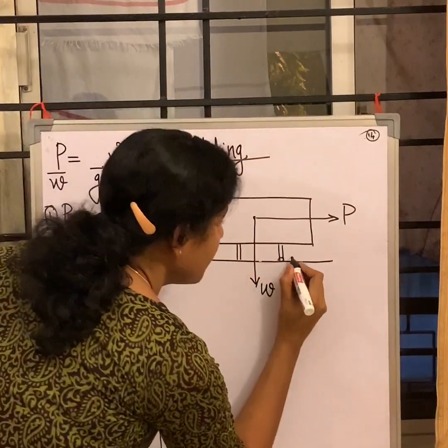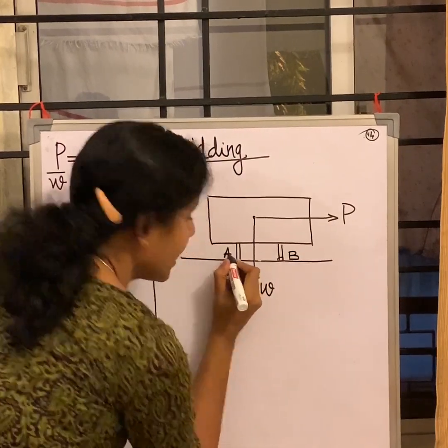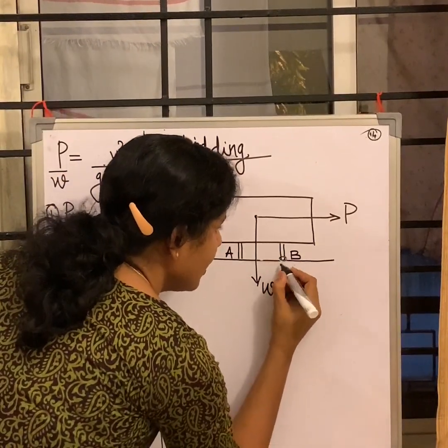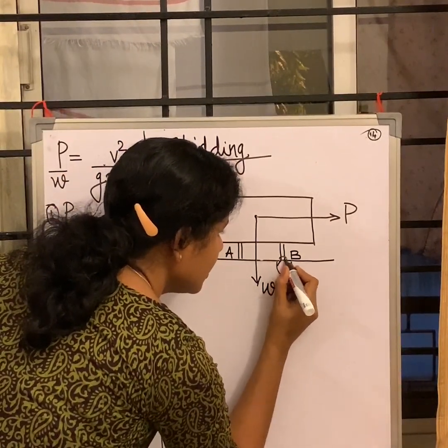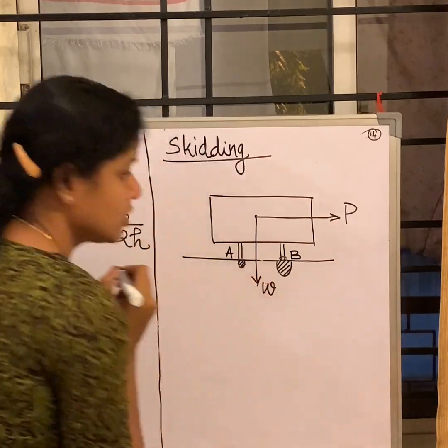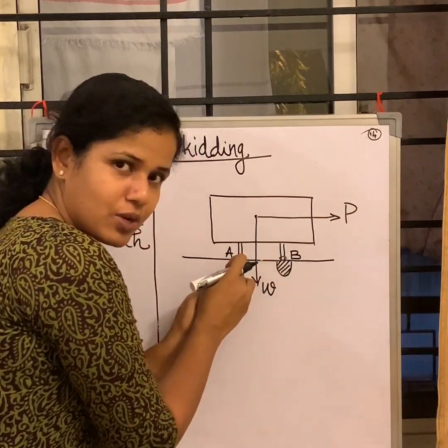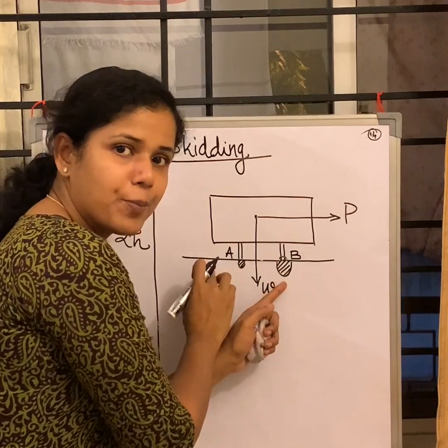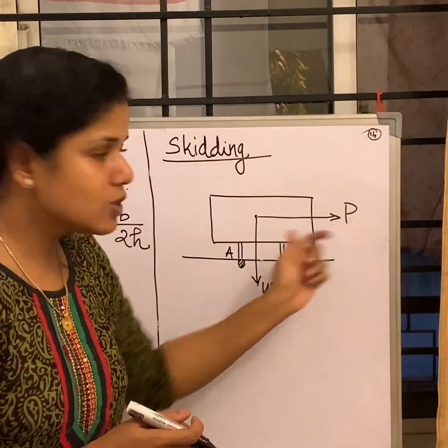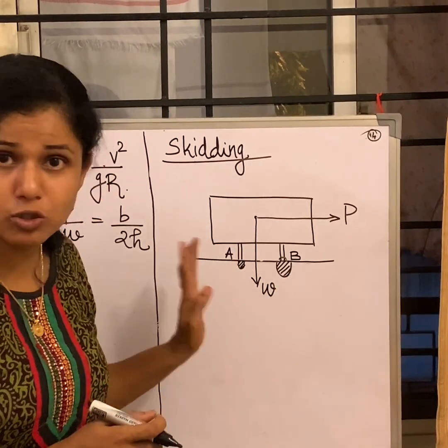But before that, please understand this is my outer wheel B and this is A. I have a reaction under my wheelbase over here, and I drew a very small reaction over here, which compared to A is slightly higher. Because we know that the effect of the frictional force is more on the outer edges, the reaction developed at B is higher compared to A.